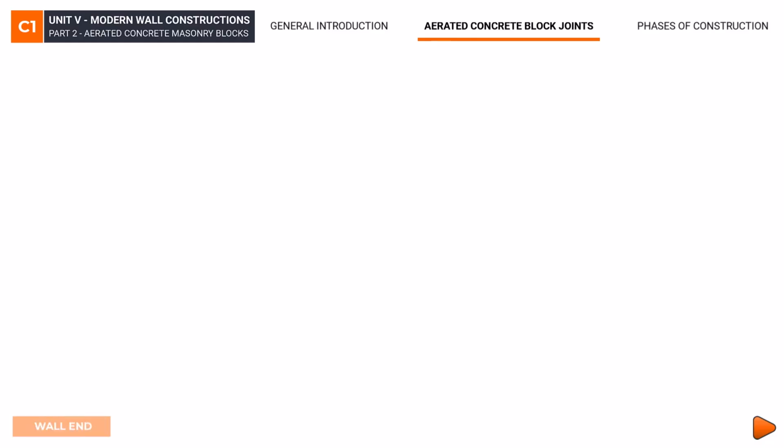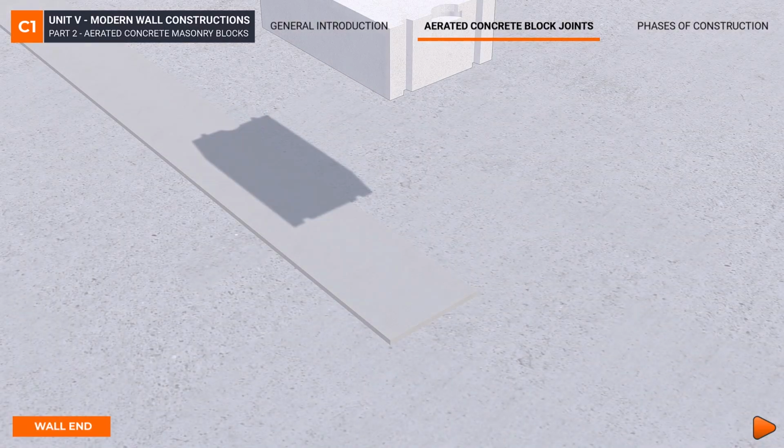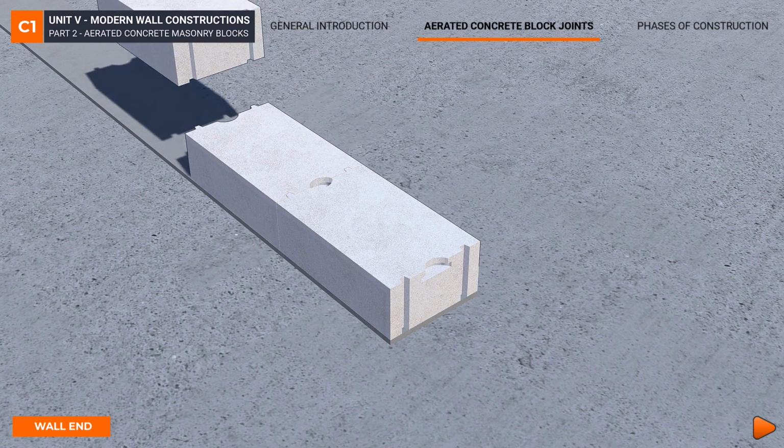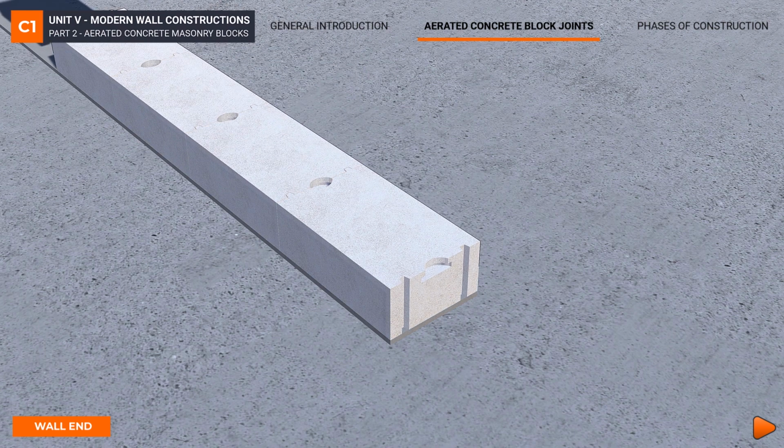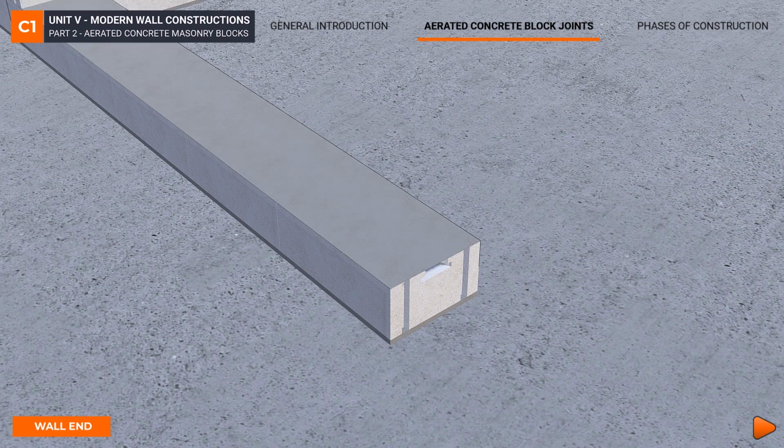3. Wall end. When forming the wall end, we also start with a whole block in the first course. In the next course, place a cut block on the wall end by the block bond plan. As previously planned, the cut blocks will be half, i.e. 30 centimeters.